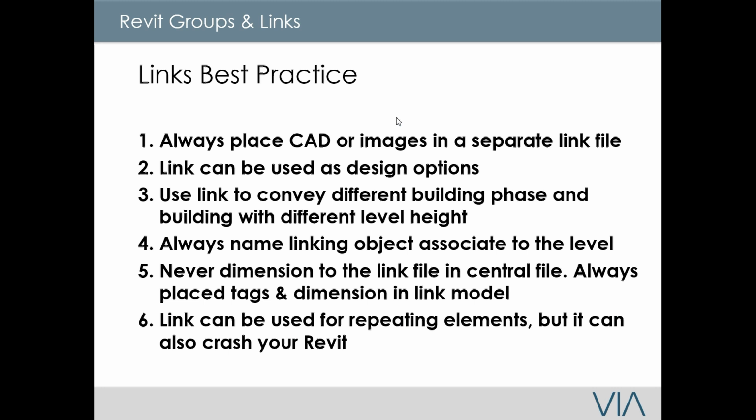Now, the second thing is that you could use links as a design option. I know that in some cases, some people like to use design options. I don't have anything against design options. In certain cases, I find links can be used in multiple ways. Design option is a perfect way to do it. The reason why I say use links is that when you finish, you can actually bind those changes, whereas with design options, the minute you say accept this as your current one, the rest of the other stuff is going to get deleted.